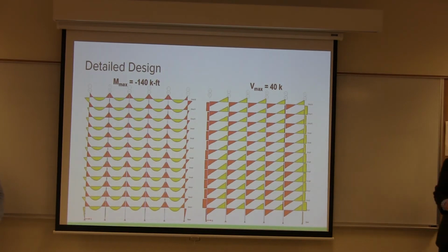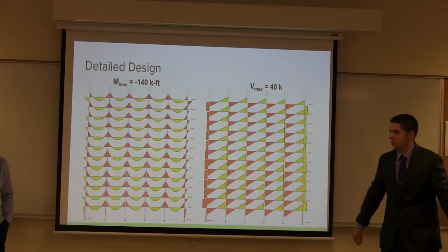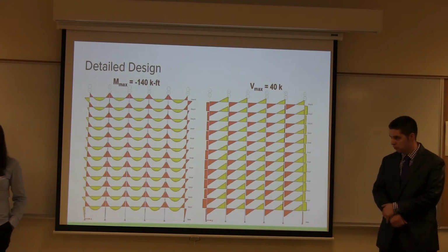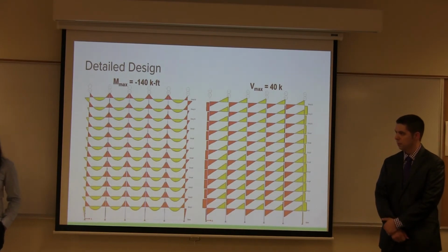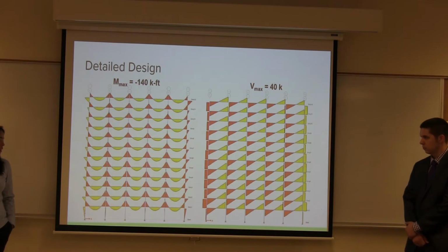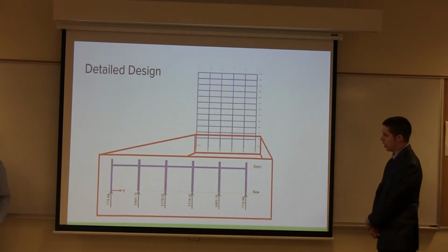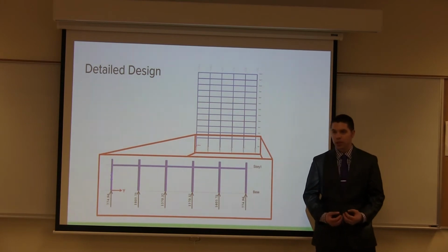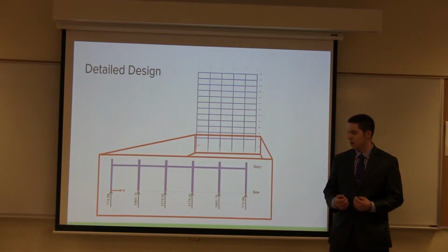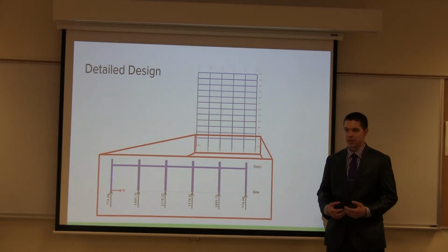Yes. Although I will verify what's on the sides, but that could be because the building will deflect a little bit to the side. So whenever you see the compression on the left, it is tension on the right-hand side columns, but that also needs to be verified. Here we have the location, which is located in the middle of the building, and this is where the highest reactions were found, all the way up to approximately 1500 to 1600 kips.